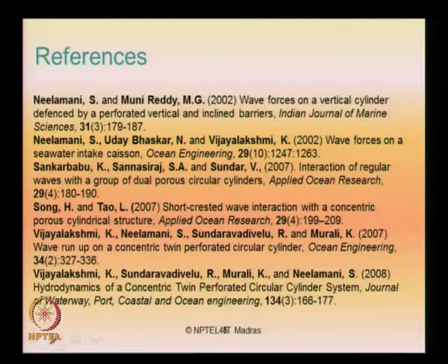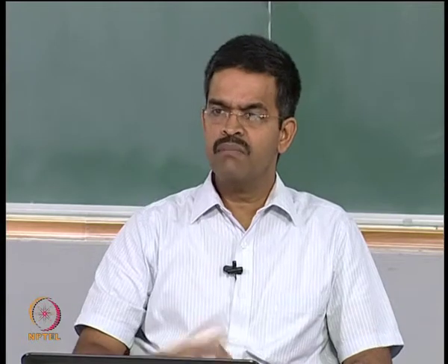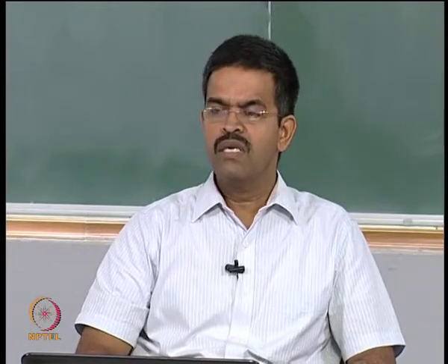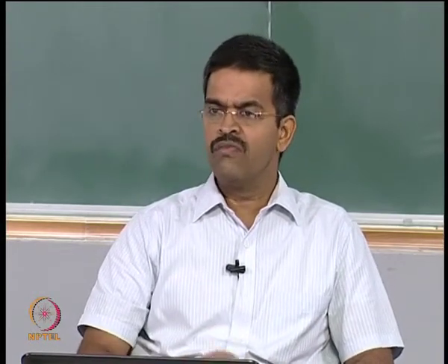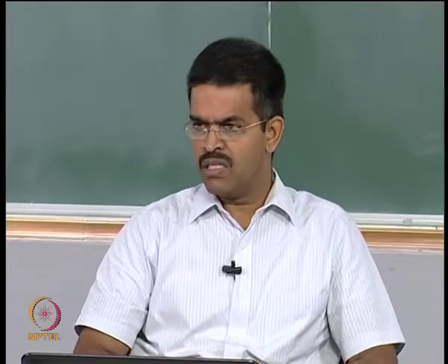We have also seen some of the studies conducted in our own laboratory by different researchers at different time periods. As you see here, people have attempted to study the aerodynamic response on twin perforated cylindrical systems experimentally and analytically. So the studies referred to, and the case studies mentioned, show that there is a significant reduction in the forces on inner cylinders encompassed by porous outer cylinders.